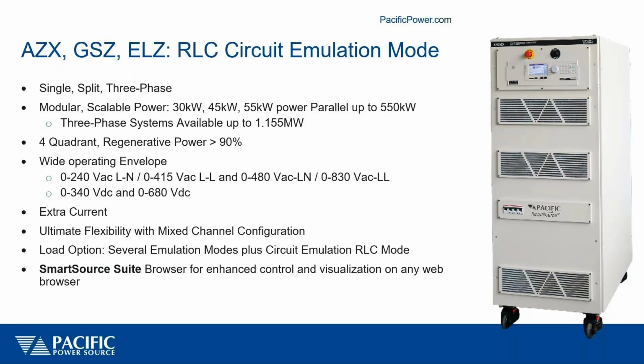Overcurrent capability for short periods of time to ride through inrush currents, and the ability to not only run single, split, and 3-phase, but also combine multiple channels. So if you had a single phase DER, you could use one channel for a grid simulator and a second channel for the electronic RLC load. So you could do a test setup with a single unit. So very flexible in that sense.